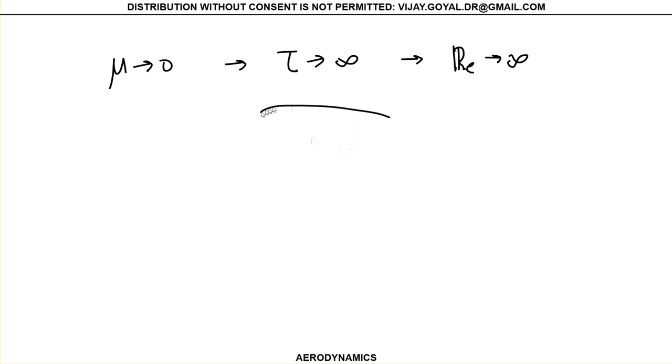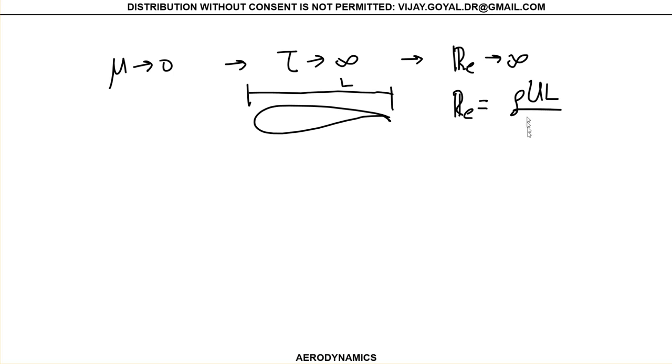One way to understand what's really going on in here is the following. Let's fix some thoughts here again. If this is 0, we know that your tau will go to infinite. And as a consequence, we also know that your Reynolds number goes to infinite. Where your L is basically a fixed value, because I know the distance over my body, that's my L. So I know this is fixed. And I know that my Reynolds number is nothing else than rho u L over mu.